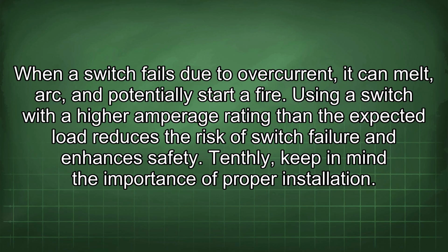When a switch fails due to overcurrent, it can melt, arc, and potentially start a fire. Using a switch with a higher amperage rating than the expected load reduces the risk of switch failure and enhances safety.